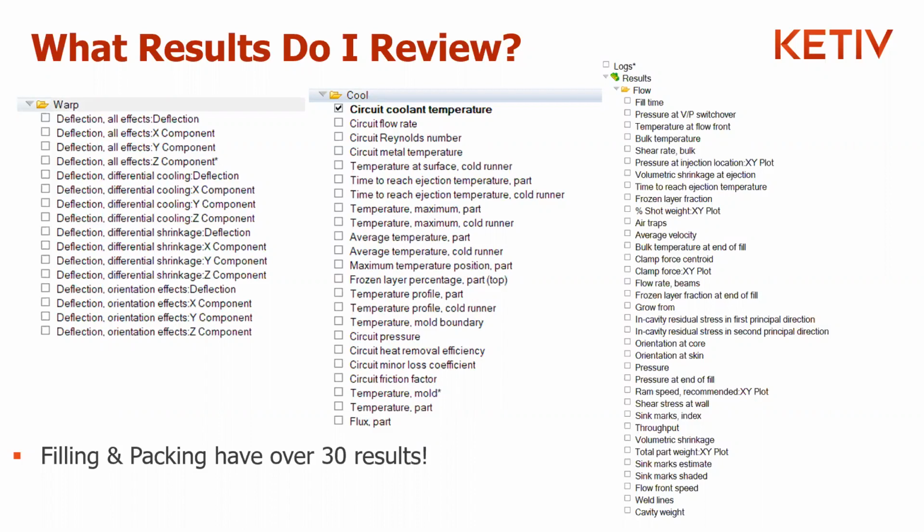And getting back to that earlier point you made, you start with a single part and it fills. Great. Just move on, right? Nope. You need to internalize that and then think about the scale up downstream. What type of feed runner system, how many cavities, that's all part of the scale up factor that needs to be considered early on as you make these choices and pick the right results. Yep, absolutely. Thank you for that, Brian.